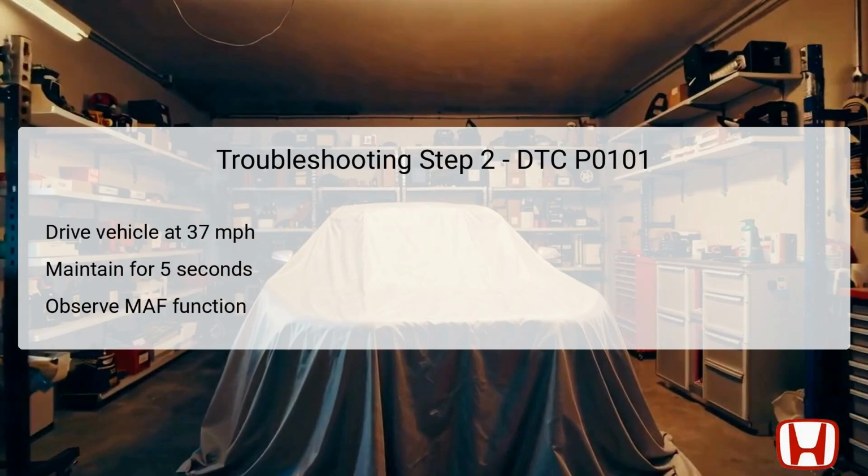During this period, the technician should monitor the MAF sensor readings, as fluctuations or irregularities can indicate the underlying cause of the DTC. The PCM continuously gathers data from the MAF sensor to ensure the correct air-fuel mixture is achieved for optimal engine performance. After this step, a clear understanding of the sensor's functionality can guide more focused inspections and repairs based on the